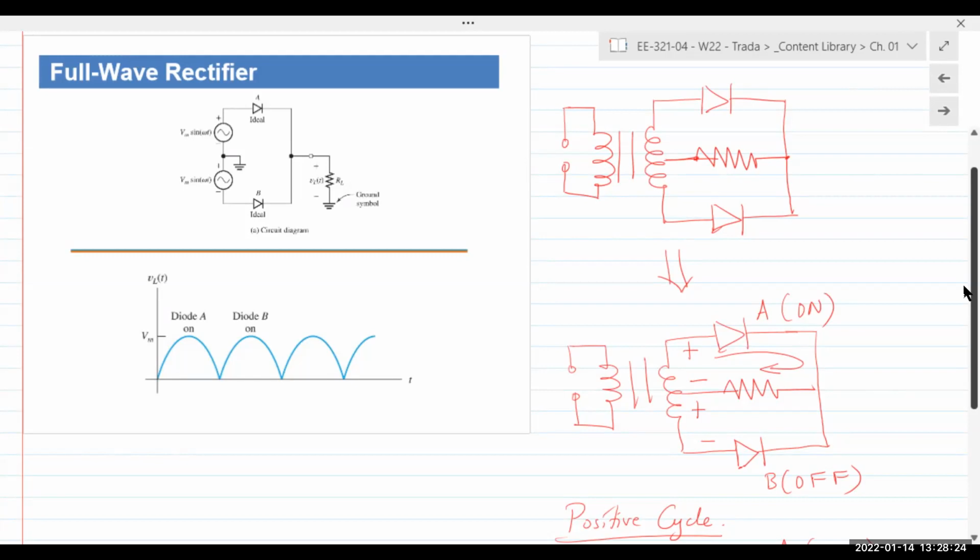Depending on where the output was, the voltage coming out of the transformer is different. You could have 25 volts, 50 volts, 60 volts, 100 volts coming out at different spots. So you change the dial, you're changing the voltage coming from the transformer, and thus the voltage being applied to that fan. Thus you're changing the speed of the motor and the wind that's coming down on you.